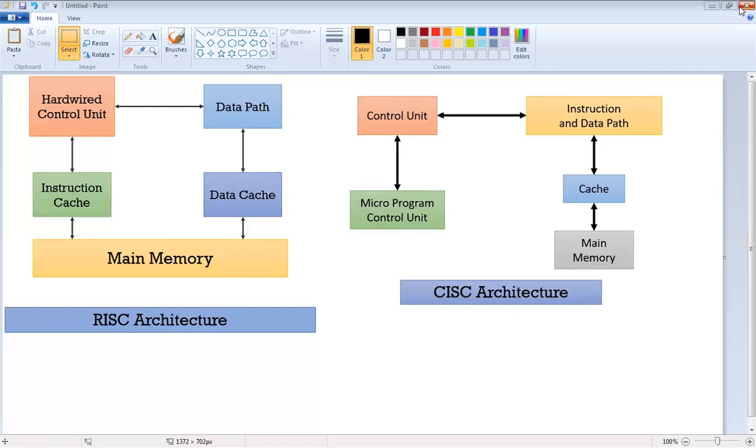It has inbuilt timers also. It has inbuilt ADC. This feature is an advantage of PIC as compared to 89C51, because for 89C51 we have to use an analog to digital converter externally in the circuit, but in the PIC controller it has an inbuilt port. One dedicated port is there which has an inbuilt ADC. Okay, it has UART for the PC communication, similar to your 89C51.